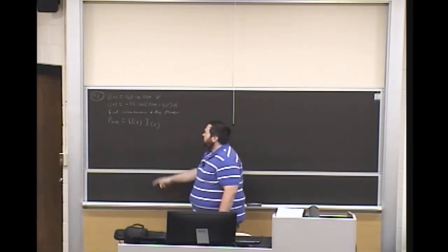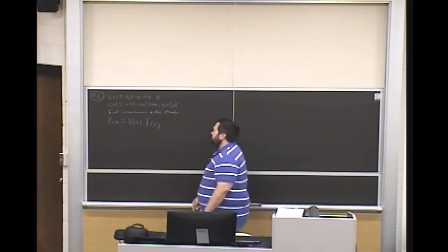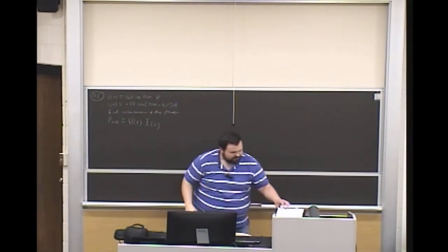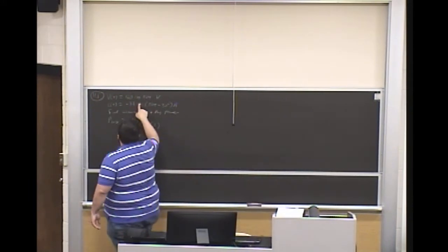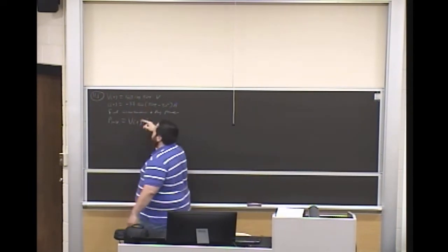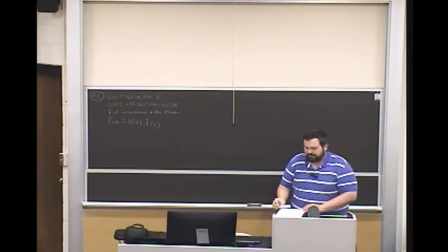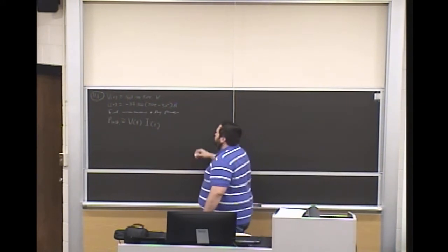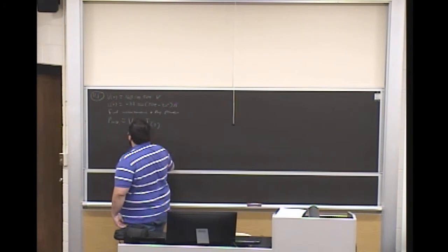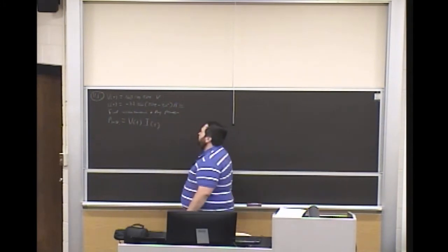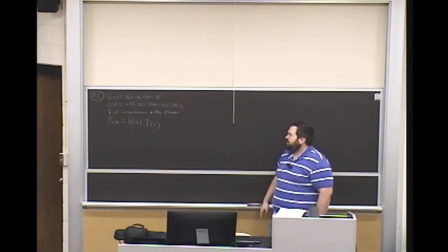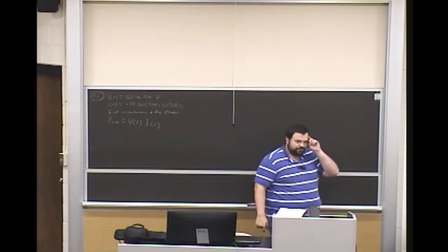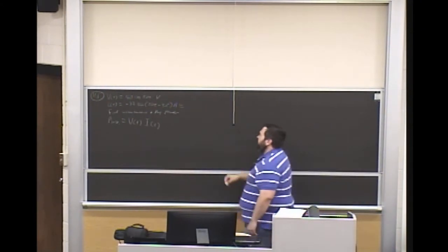Okay? And so here, if we just take these two and multiply them together, we might want to first check: is it cosine or is it sine? It's sine right here. We want to get them both into a cosine form, so that we can use one of our trig identities to multiply these things together. So before I multiply V of t and I of t, I'm going to manipulate my I of t. I want to get rid of this negative right here. How can I get rid of the negative? Add 180 degrees to my phase.